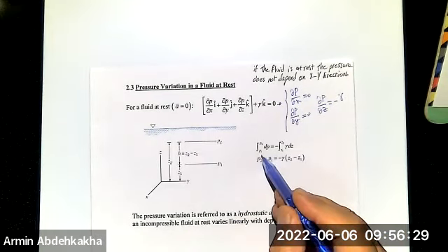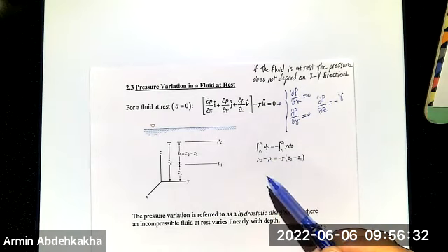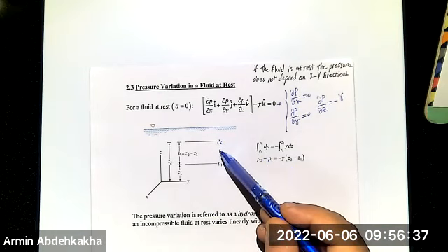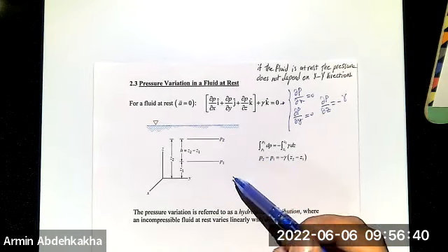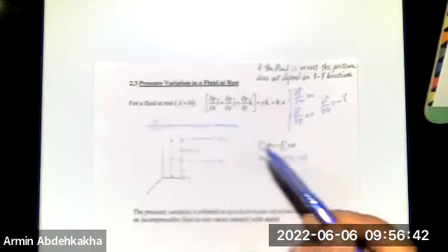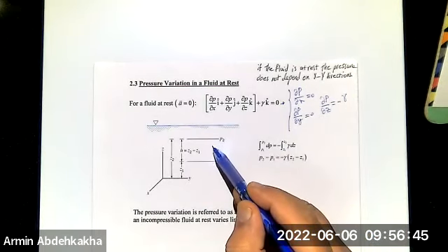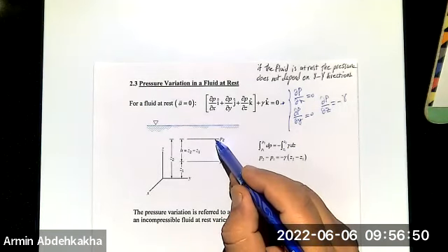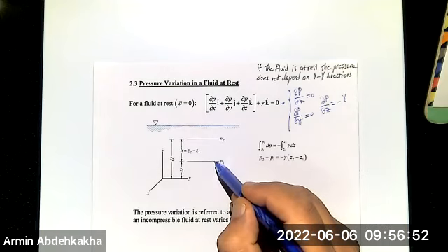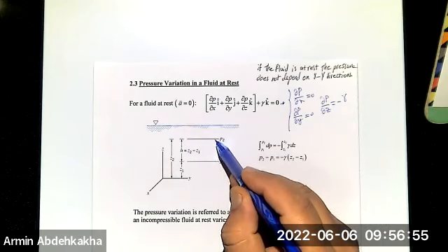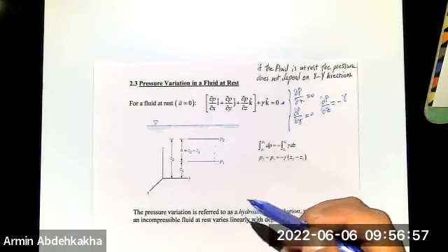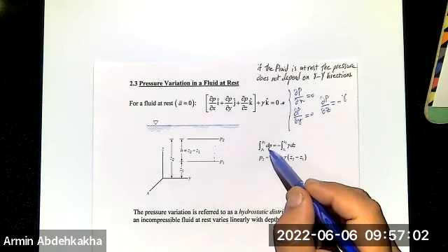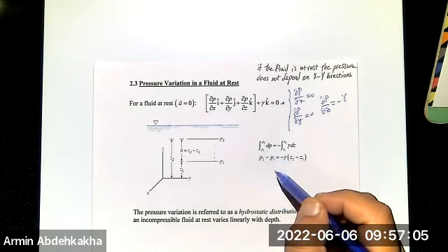So if we are going to find the delta P here, for example between P2 and P1, these two points have different depth, so absolutely the pressure point by point is going to change, right? Absolutely linear. So if the pressure here is high, then here it is low and this is higher, but it changes linearly. So we take the integral of that to find the pressure difference.